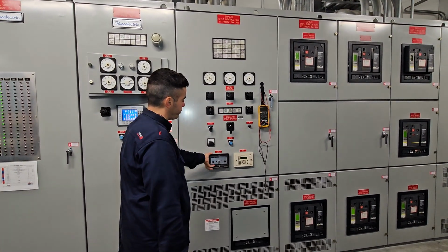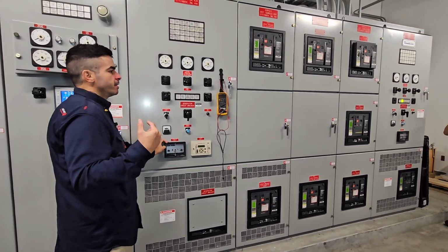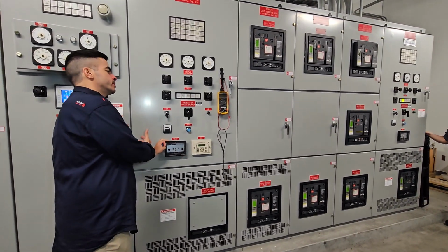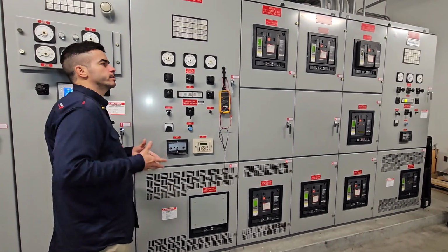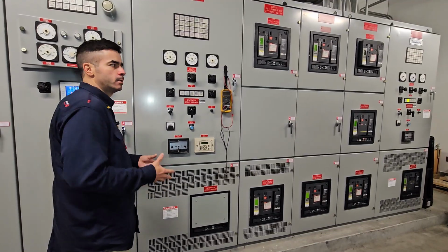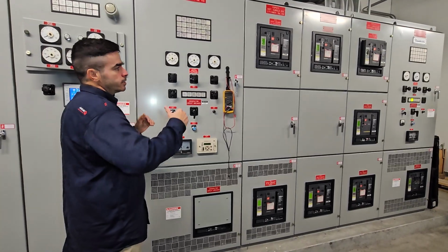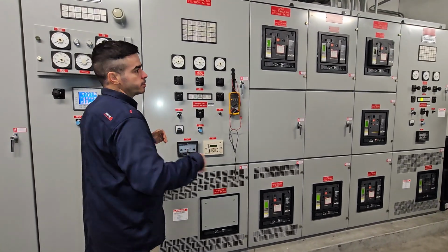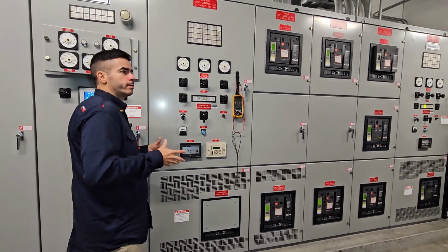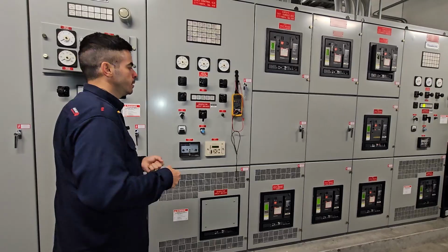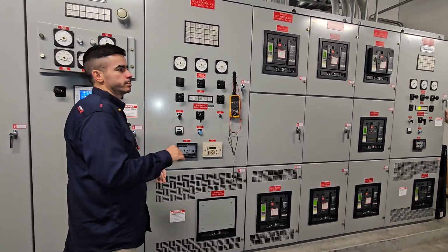When we have a reverse power relay, the reverse power relay is sensing the power that is coming out of the generator. But if it senses power going back inside the generator, then it has some parameters here that will shut down the generator, because we don't want the generator consuming power. We want the generator to be producing power, right? But there are some scenarios, if they are not in the same parameters, one generator might be producing, the other one might be consuming. So that means that instead of acting as a generator, it's acting as a motor, right? So it's getting current into it. That's not the desired condition for the generator. So this relay will protect it, it will shut it down.